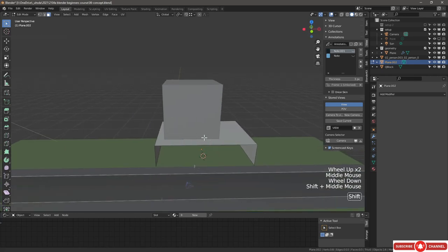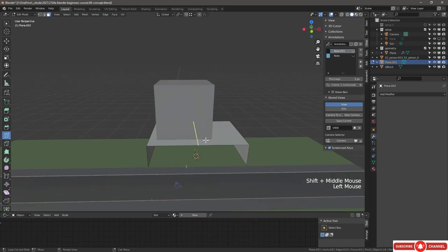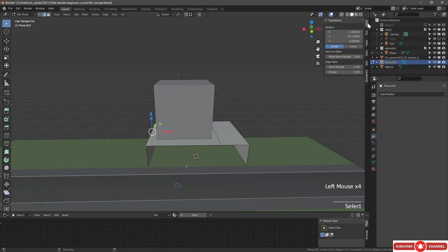Now I'm going to introduce a loop cut, so let's use the loop cut tool here. Click and hold to somewhere along there. Next, go back to selection, click on this edge, let's go into the item and change the global Z direction, and I'm seeing our object is slightly off, but that's okay. Sometimes there are rounding errors, so if you see a really small fraction, it could be just because of the way Blender works. Okay, so let's change that to 2.5.